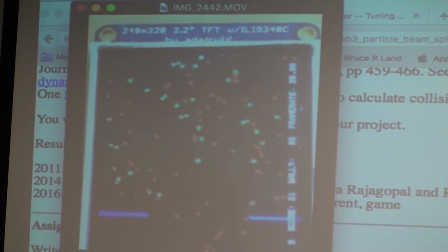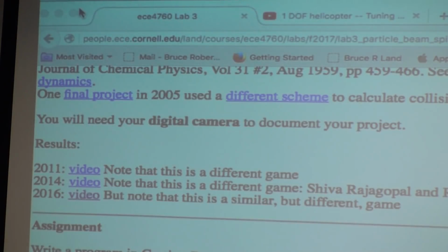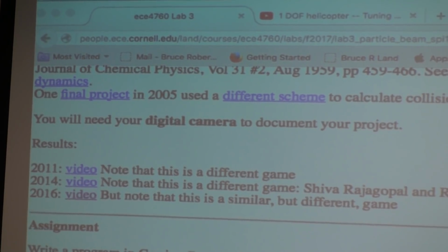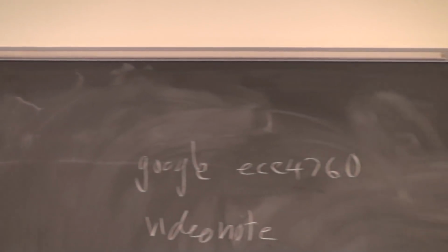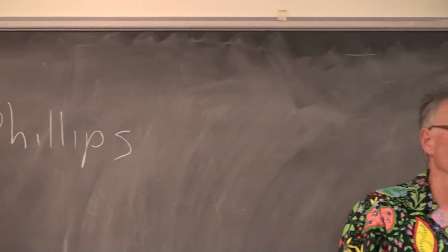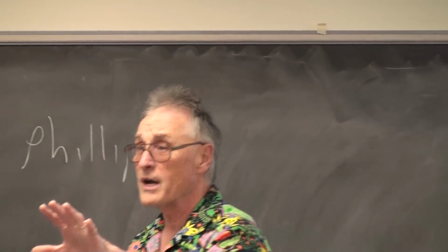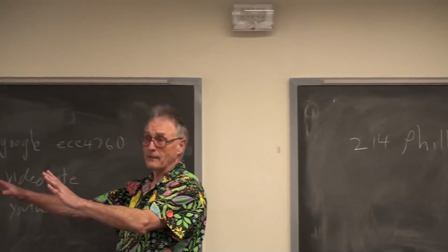And the interesting thing here is that the way we're grading this is by the number of balls you can animate. And that means this is performance-based. You have to have efficient code. It has to execute quickly. That means fixed point arithmetic, no floating point. To do the sound effects, you could use as much as 25% of the CPU unless you use direct memory access. In other words, you use this high-powered coprocessor for doing the sound. And so this forces you to learn DMA.